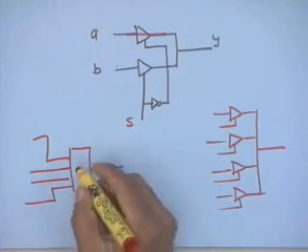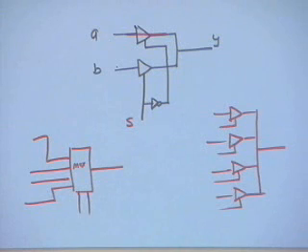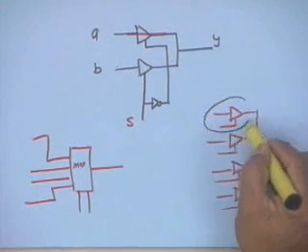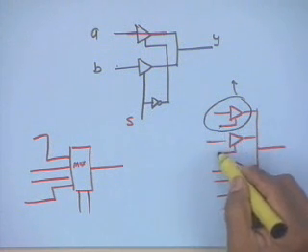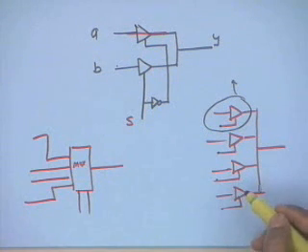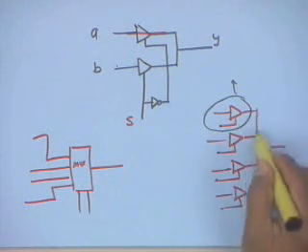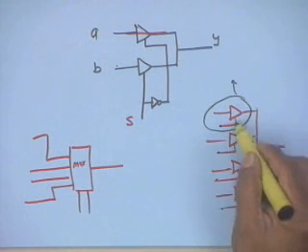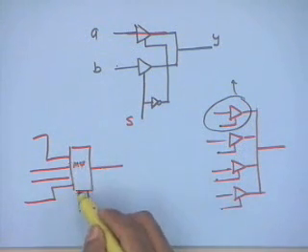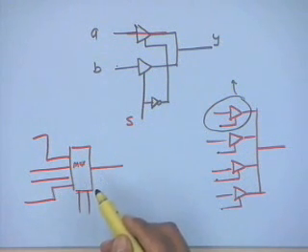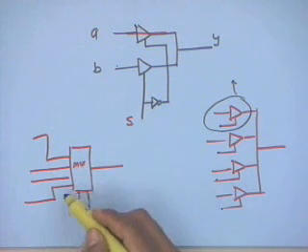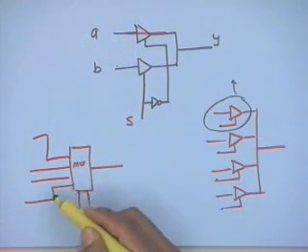the major advantage, and this we will re-emphasize when we start studying RTL components and buses, is that I can physically remove this or add this without making any changes. Logically, of course, I have to ensure that all these 4 are mutually exclusive, because obviously 2 cannot be driving this point simultaneously. But physically, not all 4 of them have to be present, whereas here you have to pre-decide that you need a 4 to 1 multiplexer to be able to select 1 out of 4. If you have an 8 to 1 multiplexer, then you can select 1 out of 8.